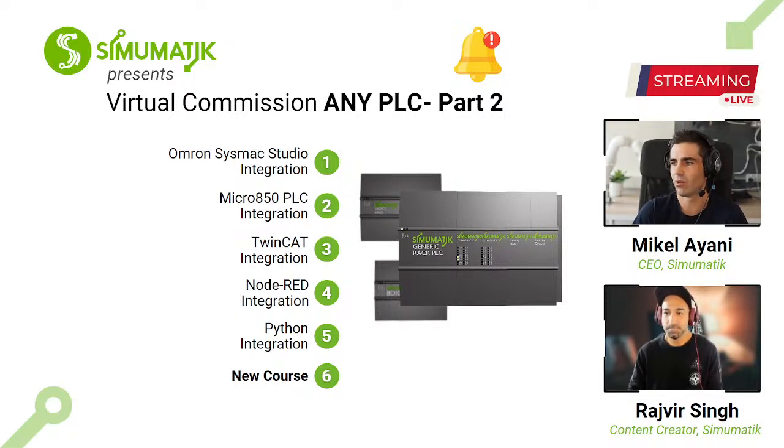I think, if not all, most of the last generation of PLCs also support Modbus. We have done a test with Codesys as well, and it's super easy to set up as a Modbus TCP server. Yes, Modbus TCP is what we're going to use. And then I take over.